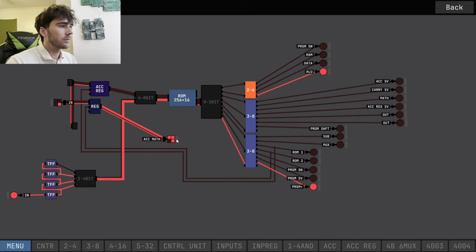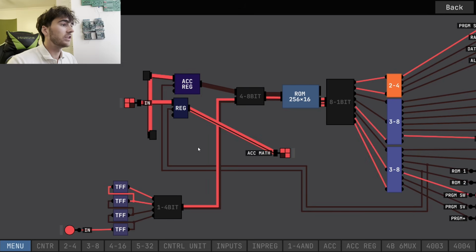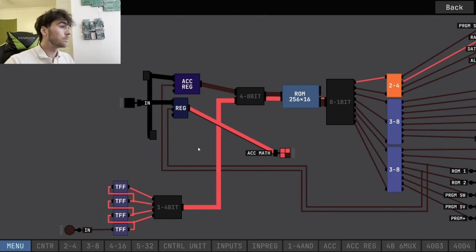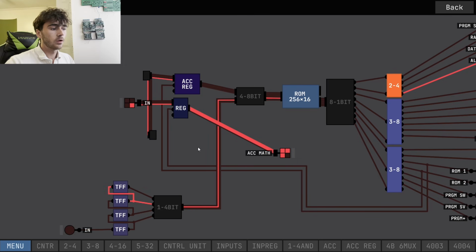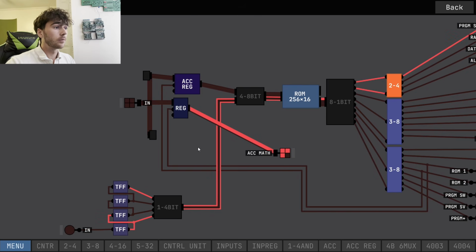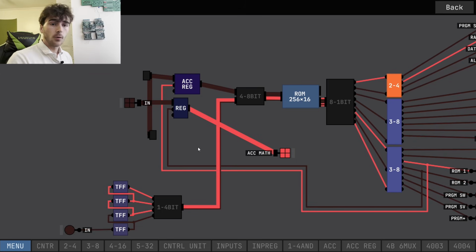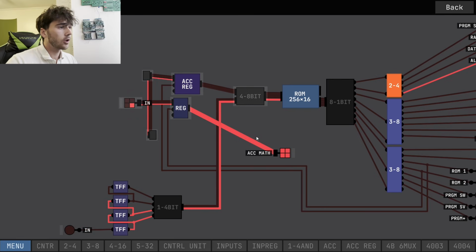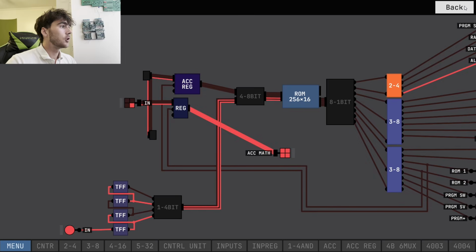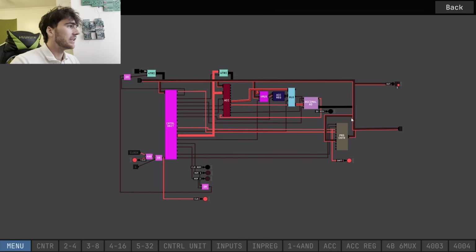And you can kind of see what I mean if you look at our control register. We have these 2 registers right here. This one's the opcode and this one's the operand. Some of them have 2 opcodes. So, for example, let's say we want to jump to, I don't know, byte 1000 in ROM. That's going to take 2 opcodes. So we're going to have to send the first opcode, which is jump, and then the next 3 4-bit spots are going to represent, hey, we want to jump to ROM 1000. My simulation doesn't even account for that because the timing is incredible. That's why there's 2 clocks, because of how hard this timing really is to pull off.